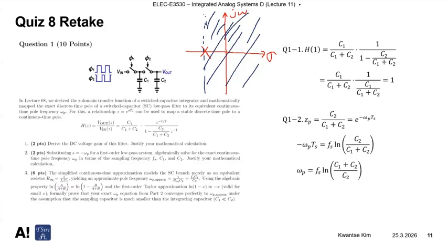And the last sub-question of question 1 is that the core idea is this. We calculated the accurate pole frequency of this transfer function, and can we approximate it to a bit less accurate one, which excludes the effect of the C2 capacitor, just modeling this C1 and switches as 1 over Fs C1, right? That goes to switched capacitor resistance.